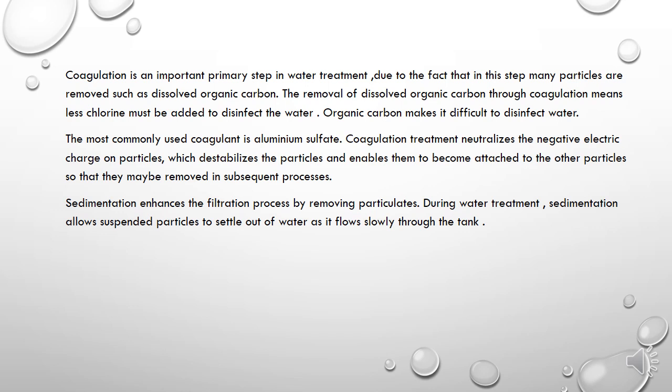Coagulation treatment neutralizes the negative electric charge on particles, which destabilizes the particles and enables them to become attached to the other particles so that they may be removed in subsequent processes. Sedimentation enhances the filtration process by removing particulates. During water treatment, sedimentation allows suspended particles to settle out of water as it flows slowly through the tank.